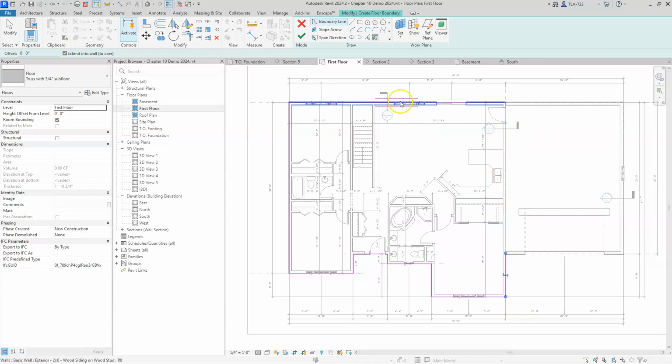I'll show you an easy way to do that. We're just going to click Trim Extend to Corner, and pick this line and this line to extend that single line all the way up. I could have picked this wall and had two segments in this boundary edge, but that's usually not best practice, so avoid that when you can.